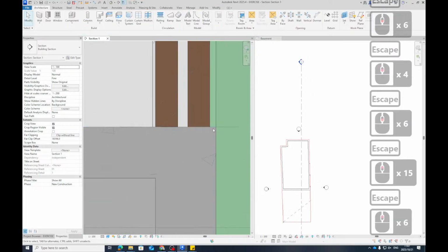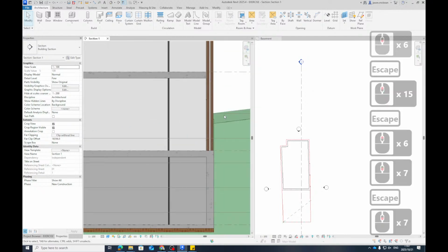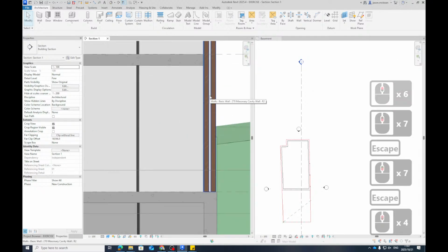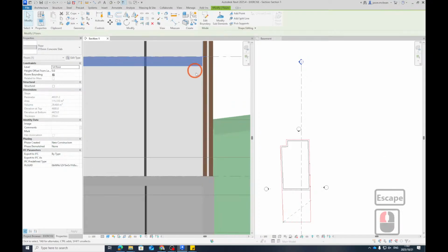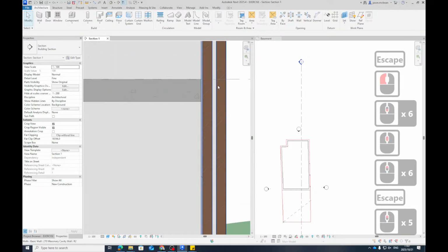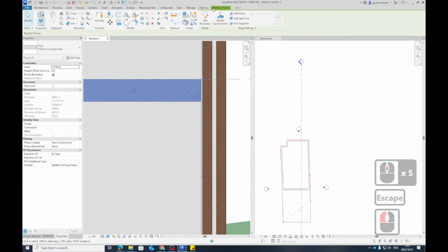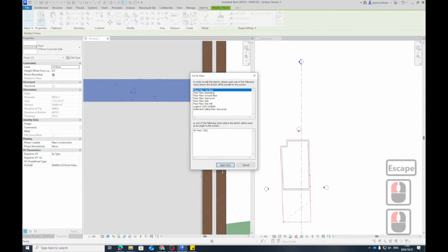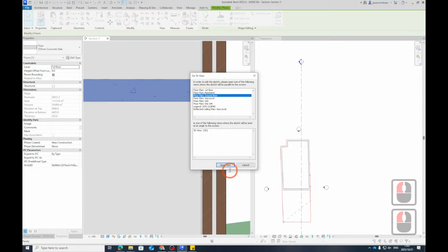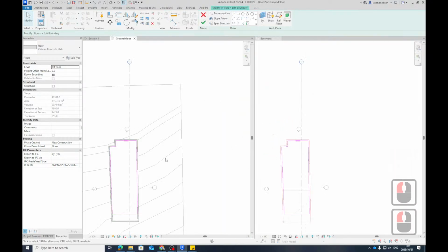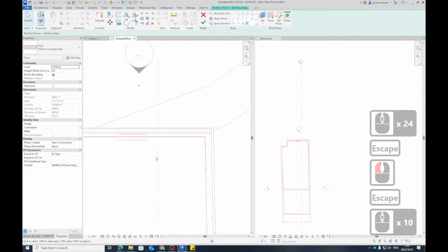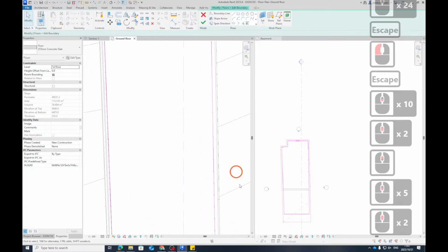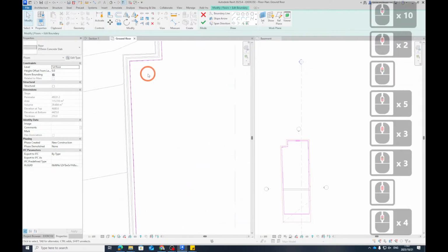Then we've got some weather strip we can do here, and here's your cavity wall. Because in the Cape, you get a lot of wind-driven rain, you're going to need a cavity. Okay, it's very wet there. Now, technically there's a beam that sits in here. So what we tend to do, I go and edit boundary, so just make it ground floor. What we tend to do is we put this into the, oh, that didn't change, so I don't know why. Okay, so that one wall still a 220 masonry wall, but this is a good example.